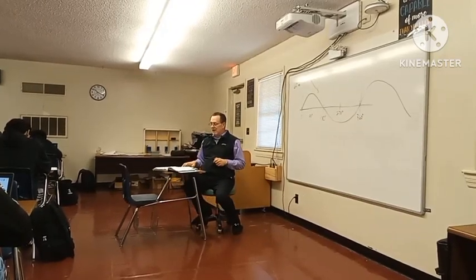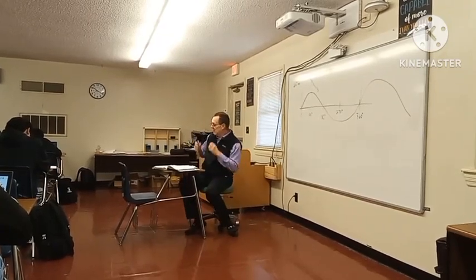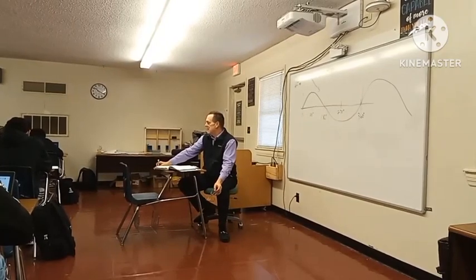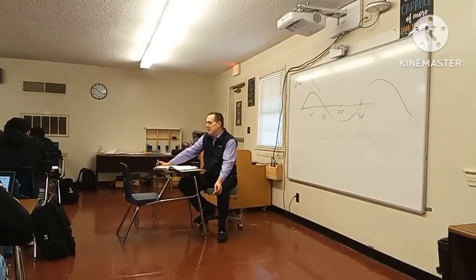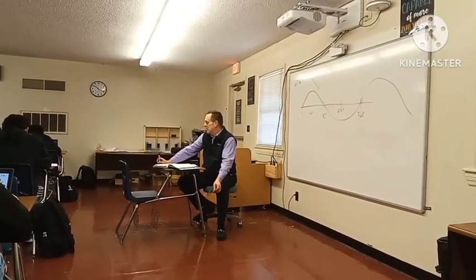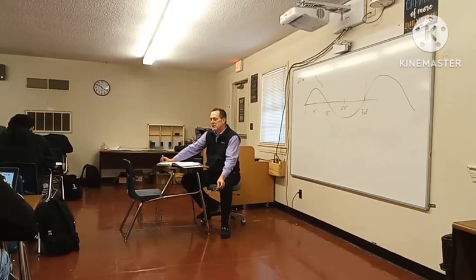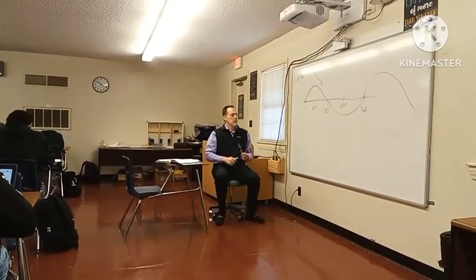What we're going to get to figure out is the root mean square. When you read your meters and we're testing the voltage, that's basically the reading you're going to be getting. It's going to be giving you a voltage reading. When you're reading AC voltage, you're reading on that meter basically the root mean square of that AC waveform, right?